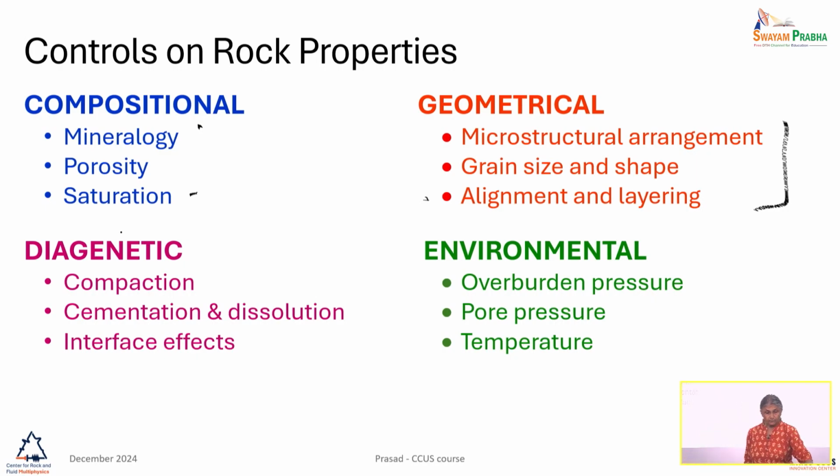And then we have time dependent changes, where we have compaction just from the overburden, everything lying on top. We have cementation, dissolution, and we have interfacial effects on fluids that are adhering in 1-2 monolayers to the surface that act almost as solids. And so there are effects of these, almost diagenetic for most of the cases.